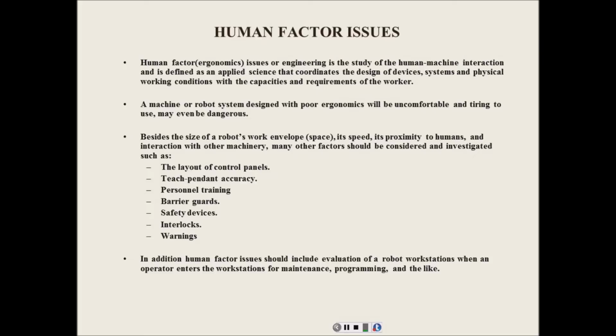Of course, I was doing some reading, and why they like T1 on these production robots is so they can actually get the true cycle time for the robot. Probably 99% of robots in manufacturing, probably around 90%, the programs are repetitive programs, which means they do what? They come down, they do cycles. They'll start in a home position. They'll come down, they'll do something, they'll move around, then they'll come back to the home position and wait on something else, and then they'll do it again.